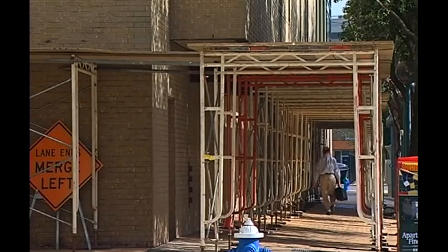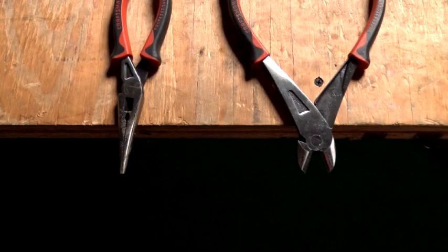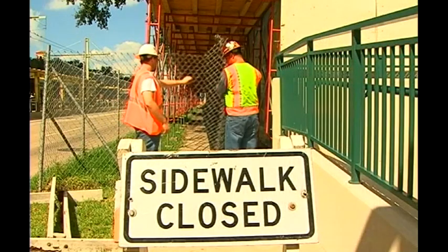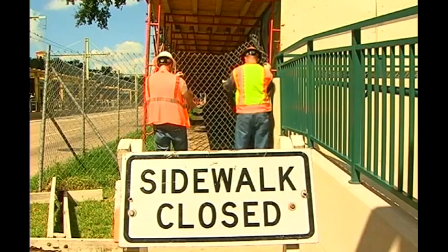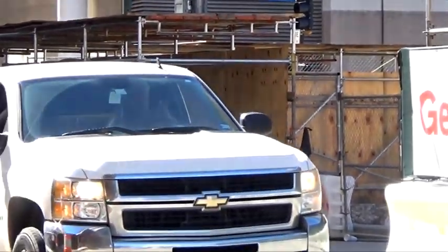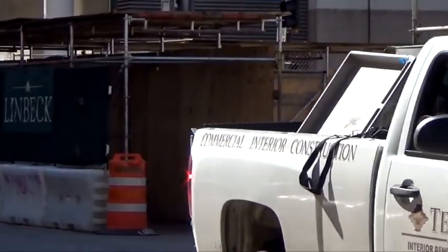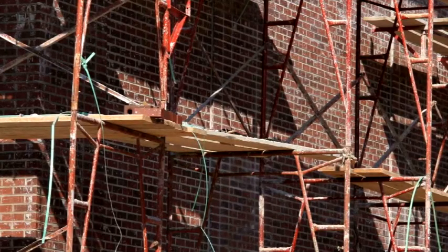Erect canopy structures and keep potential falling objects far enough from an edge, hole, or opening to prevent them from falling to a lower level. Or, the employer can barricade the area into which objects could fall, prohibiting employees from entering and keeping objects far enough from an edge or opening to prevent them from falling to a lower level.